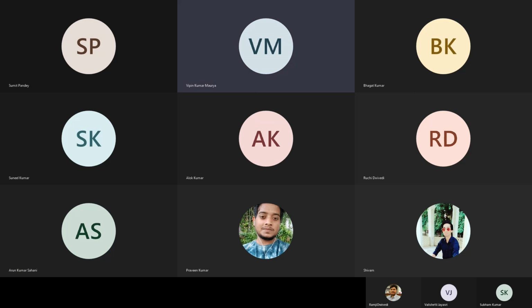That value we have taken just for an example. At that time, we were requiring the xyz for a location, x naught, y naught, z naught for a reference point, and lambda naught, phi naught. So that xyz may be any point. We are trying to compute easting, northing, up with reference to the known reference point. I can give you any value of xyz. That x naught minus 5, y naught minus 5, z naught minus 5 was taken just for an example.